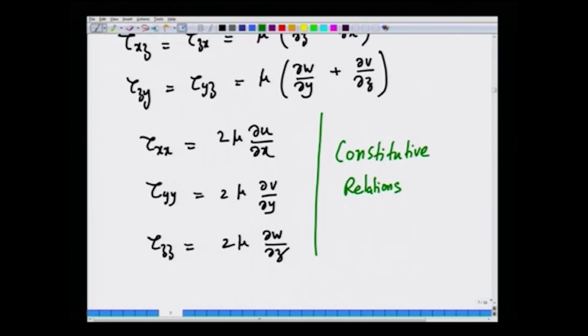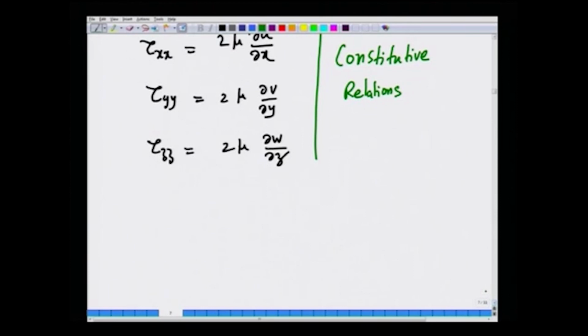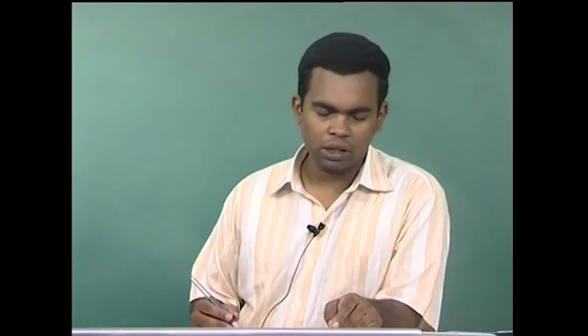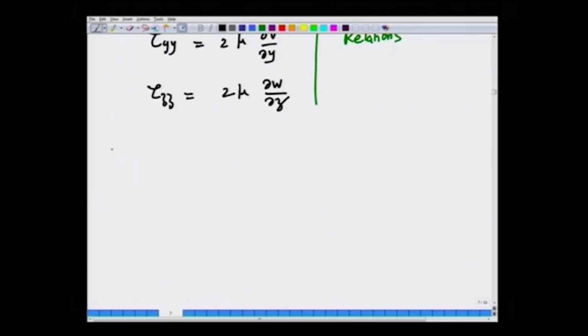Now, we have written all the stresses in terms of the velocities or gradients of velocity. So, we have exactly the same number of equations as unknowns, because we have 3 momentum equations and 1 continuity equation, and 3 components of velocity and 1 pressure as the unknowns. That completely specifies the problem. So, now let us substitute all this in the momentum equation, step by step.